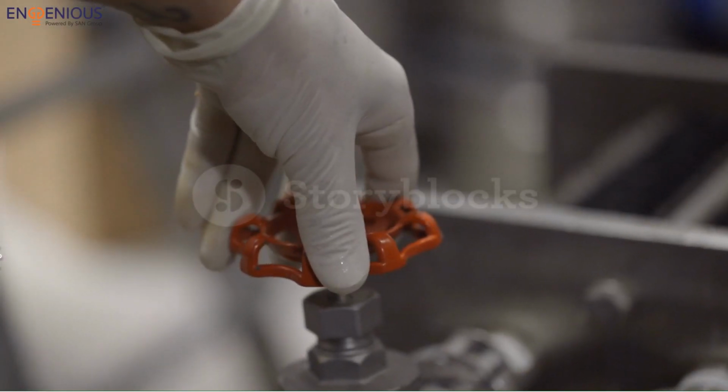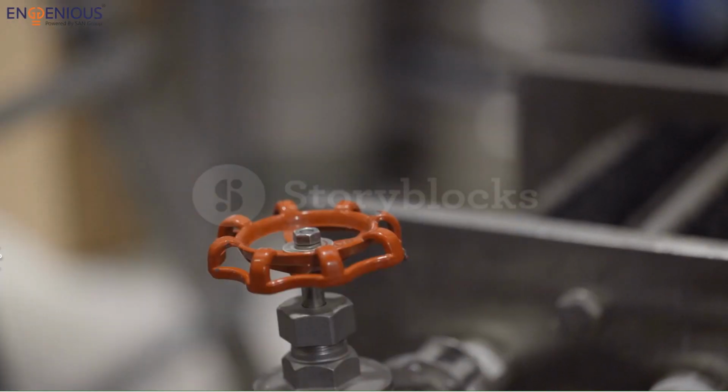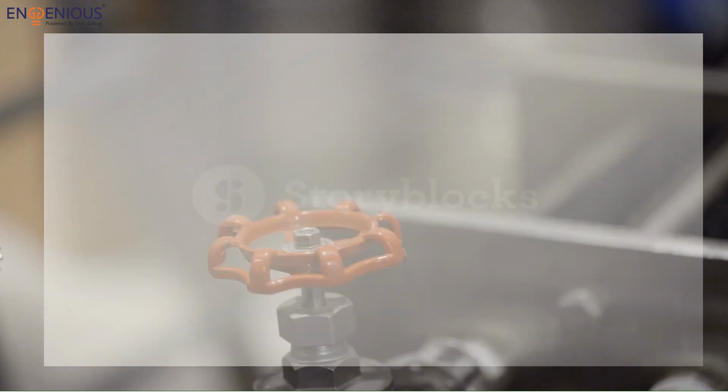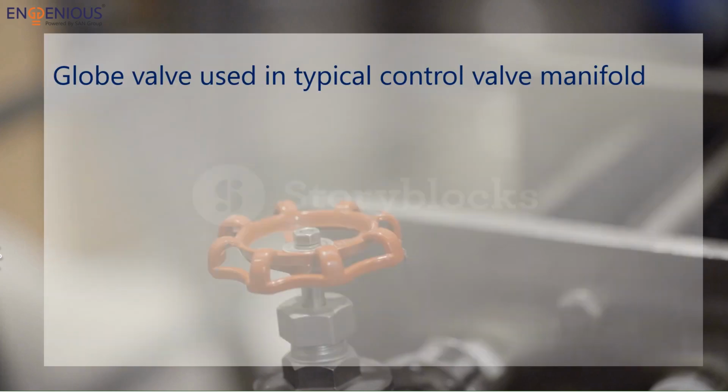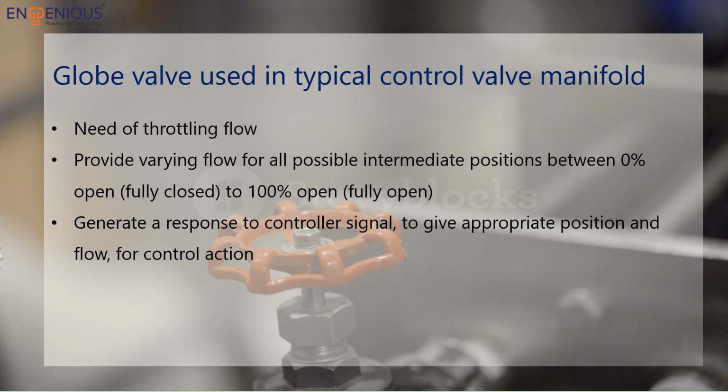Globe valve is a device that regulates the flow of one or more fluid process streams. In the context of control valve manifold, the process side requirements are: need of throttling of flow. There is need to provide varying flow for all possible intermediate positions between 0% open to 100% open. Generate a response to controller signal to give appropriate position and flow for control action.